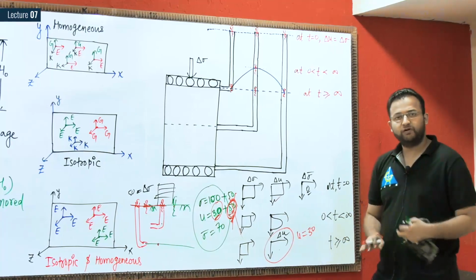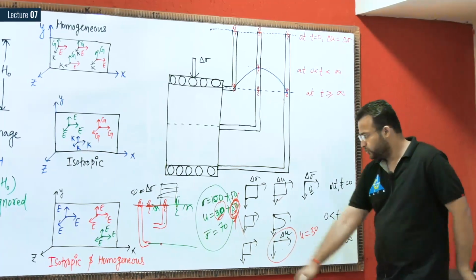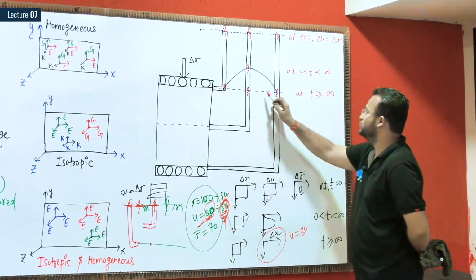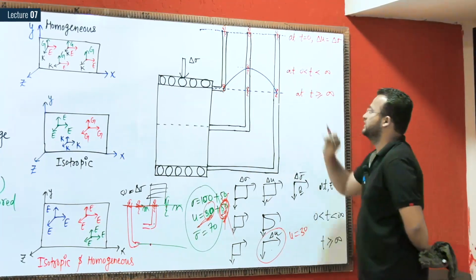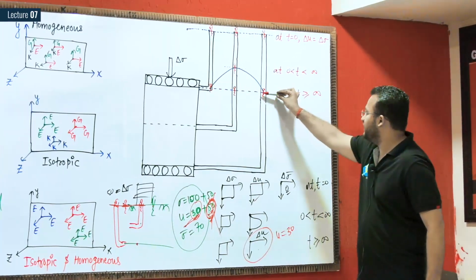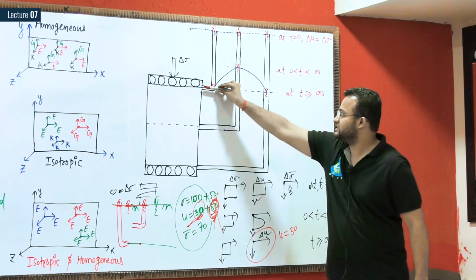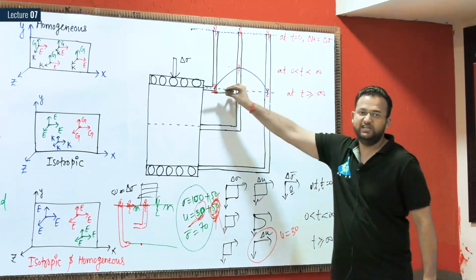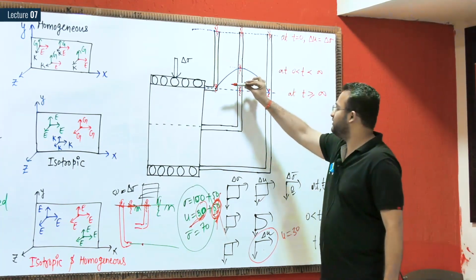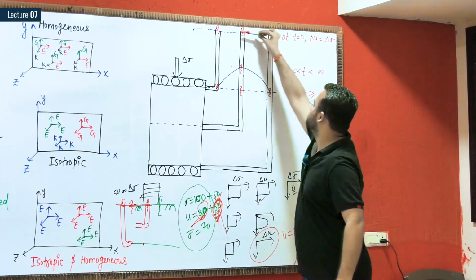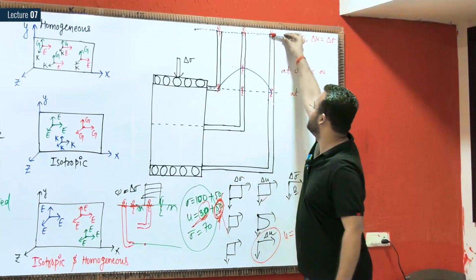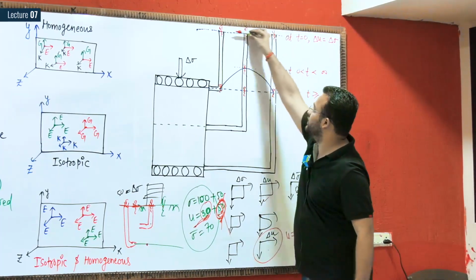The complete excess pore water pressure is removed. So U will become again equal to 30 only. So you can see again it has reached the initial values of pore water pressure. Are you getting my point? This line we have started, this is the initial line of pore pressures, when there was no building. We have constructed one building, pore water pressure increased up to here because the complete weight of the structure has been taken by water. So pore water pressure is increased up to here.